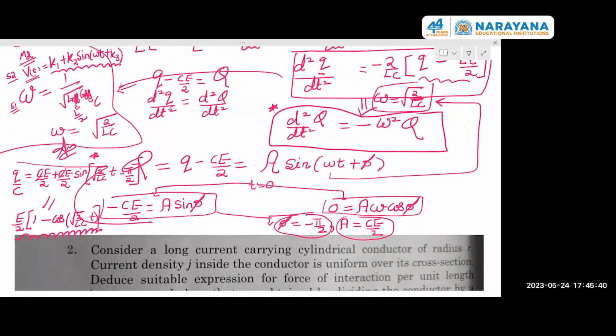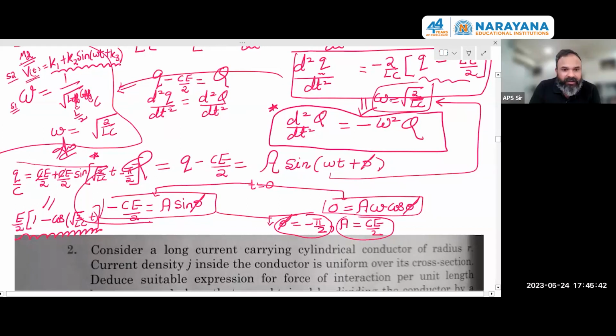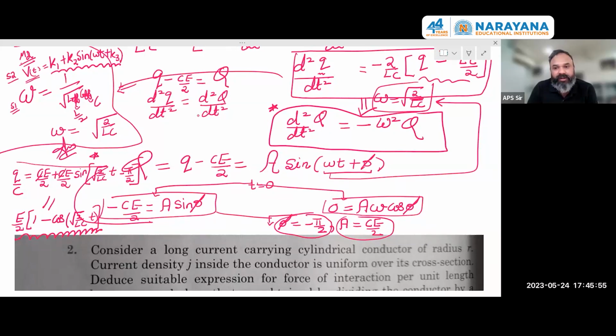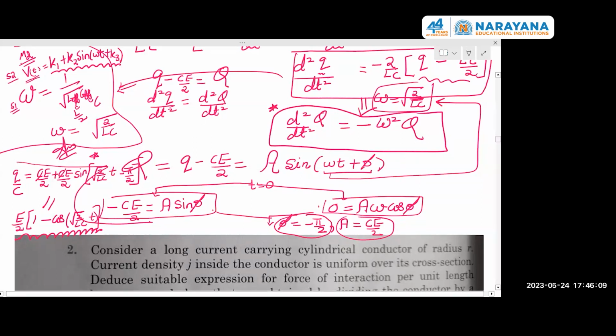Yes, sir. So the reason I have taken this as minus is because the initial phase for the current should be decrementing from that point, right? I mean, yes, sir. This function is going to decrement. So I need to consider that into the picture. So not only am I optimally looking into the trigonometric solution, but I'm also observing the physical behavior of the circuit. Because LdI by dt should be 0 now. Yes, sir. So that's what I have done.